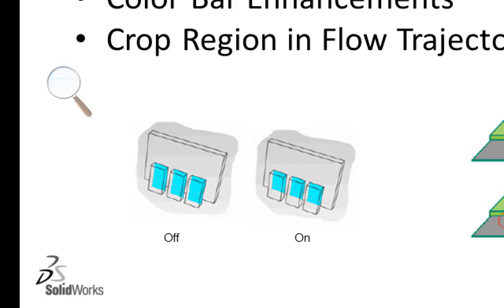Now in 2012, and in Flow Simulation 2012, you no longer have to go in and create the split line. You can actually choose the two touching surfaces, and when you click on this little checkbox for apply to solid only, it will ensure that you're only applying this condition to those touching surfaces.